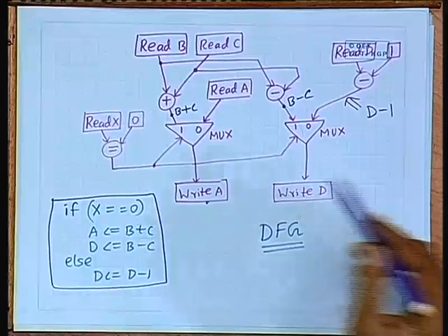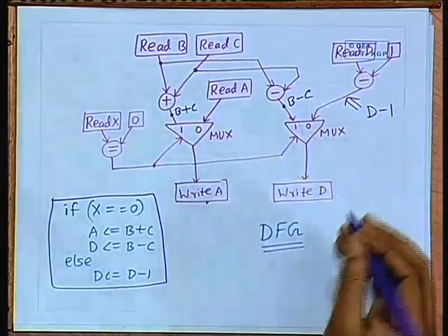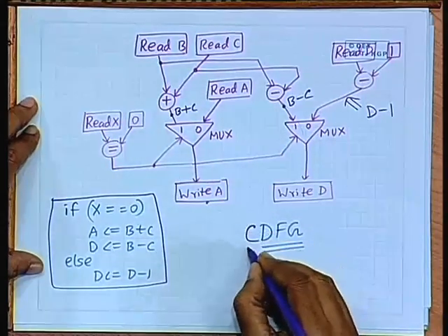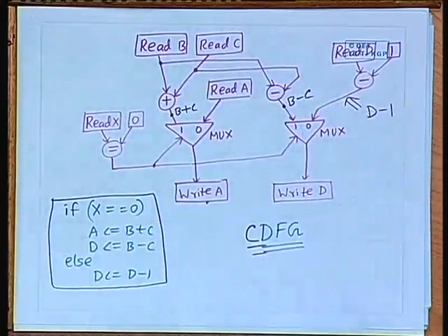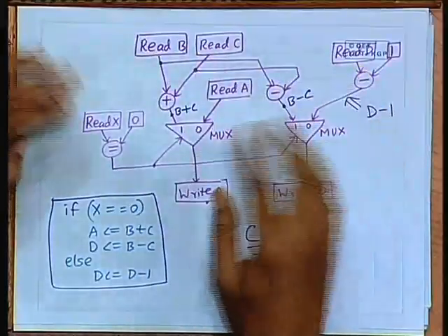Right. So, this diagram essentially combines both control and data. In fact, this is CDFG now, control data flow graph, both together. I have drawn this just for the sake of convenience. Actually, in the implementation these registers will not be scattered like this; there will be some register bank kind of thing, and some reads and writes generated for that. It will be more complex, but just for understanding the basic concept I have shown you these examples.